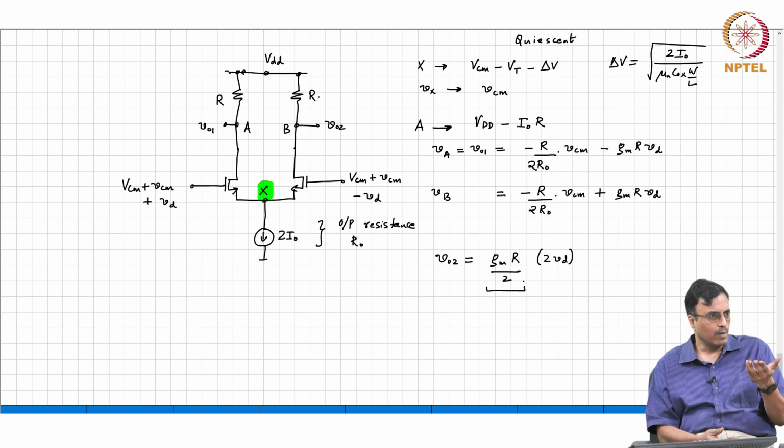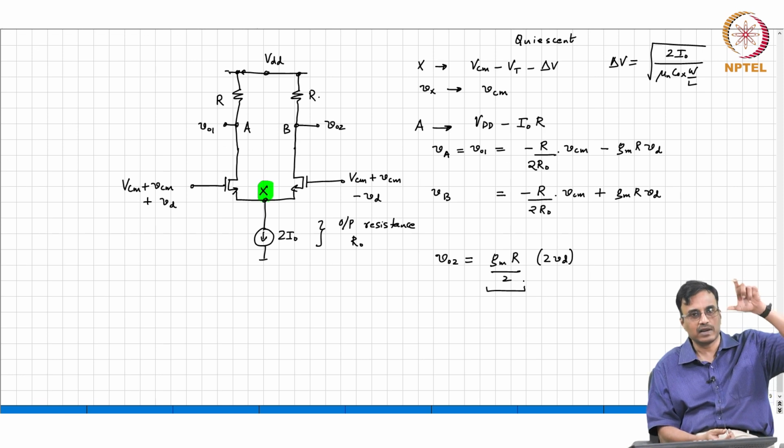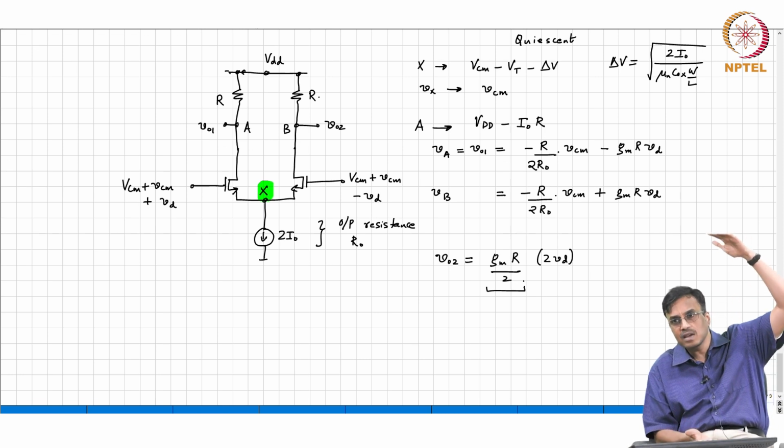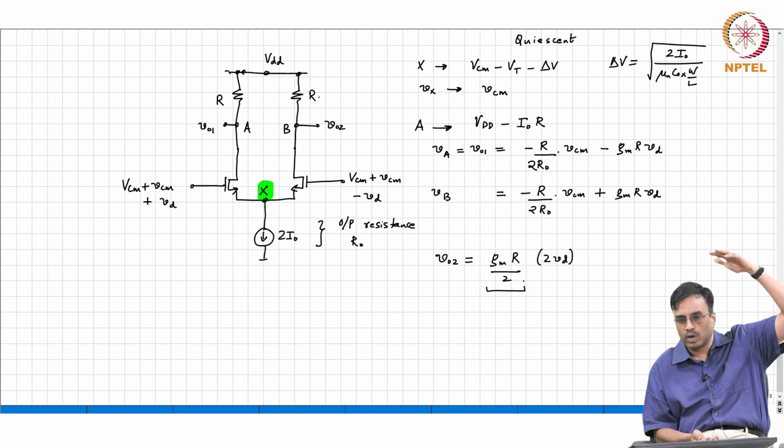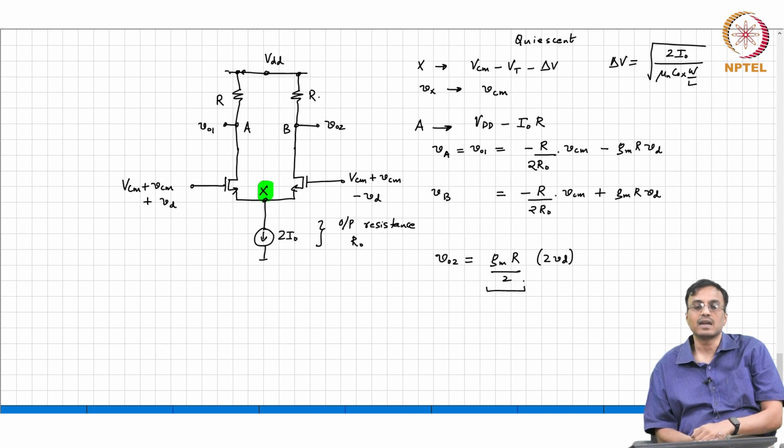For a given supply voltage, as you keep making R larger and larger, you can't get too greedy. Eventually the transistor will go into the triode region, correct. And the only way to fix that problem, if you wanted to keep a resistive load, was to keep increasing the power supply voltage.